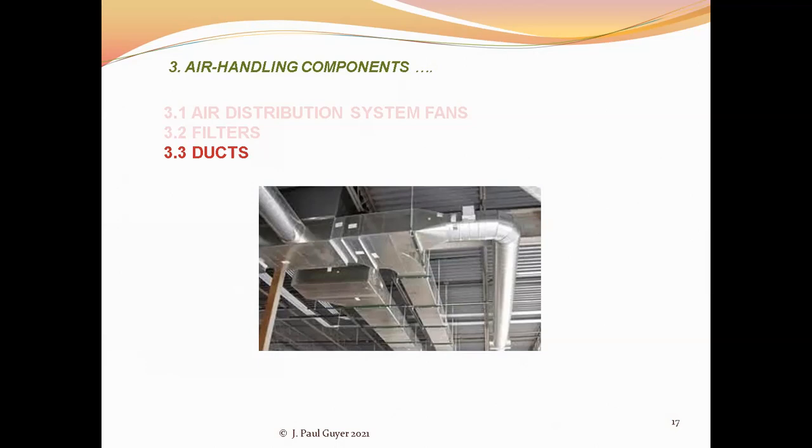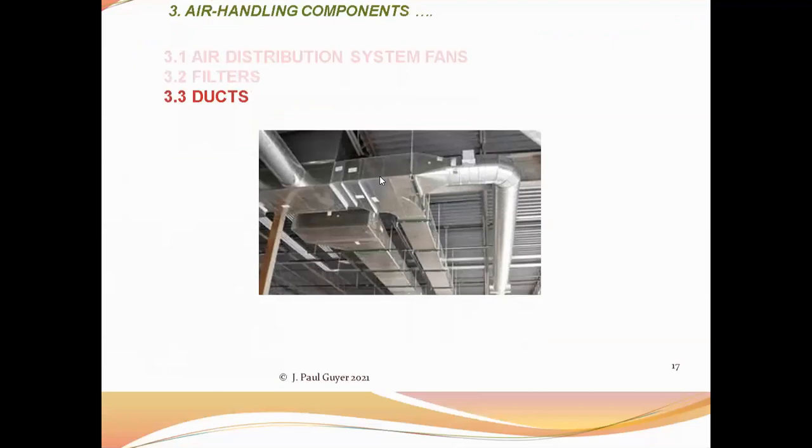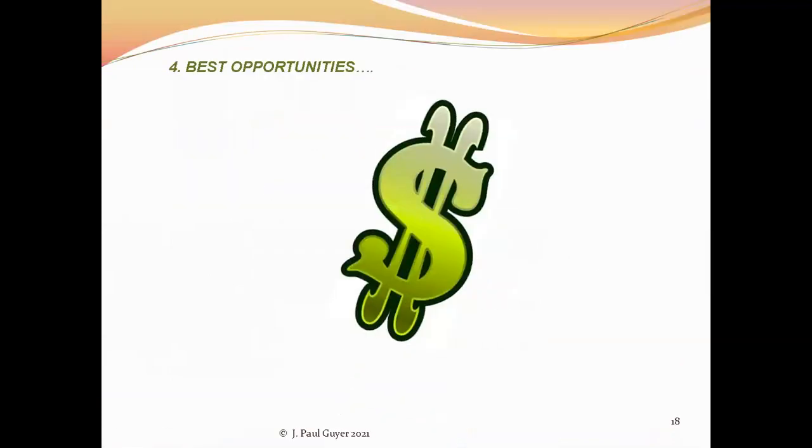The ductwork system either was designed with energy efficiency in mind, in other words, using round ducts where possible, because they are more energy efficient than rectangular ducts. But the rectangular ducts may be necessary in order to duck around tight spaces and things like that, and move around the building. So this is what you've got to play with, essentially.